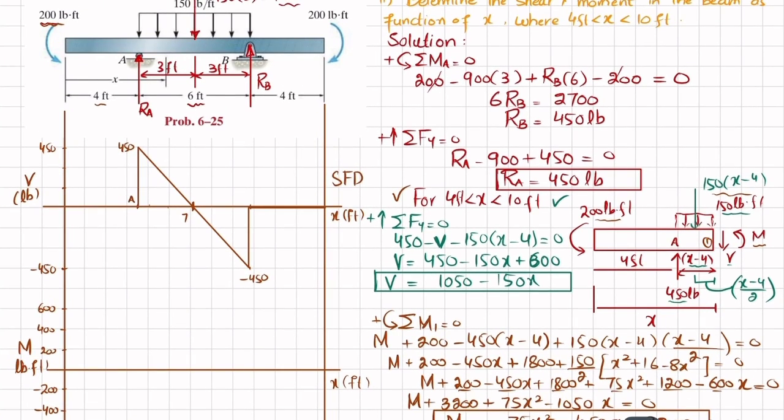Now at this point you can see you have a counterclockwise moment of 200 pounds into feet. So while drawing the bending moment diagram, it will cause the movement toward the negative side, downward, because this is given and this is the convention mentioned in the book. So your first point will be this one. Clear? Now from this point till point A, there is no other moment, so it will remain horizontal up till this point. So this will remain like this. Okay. At this it will be minus 200.